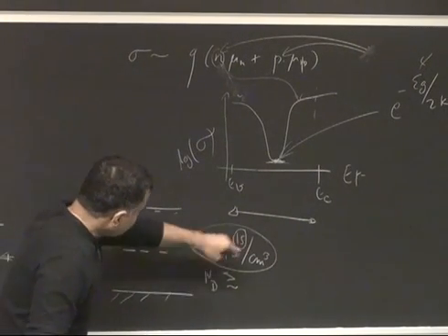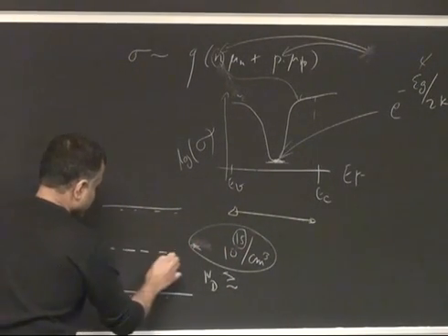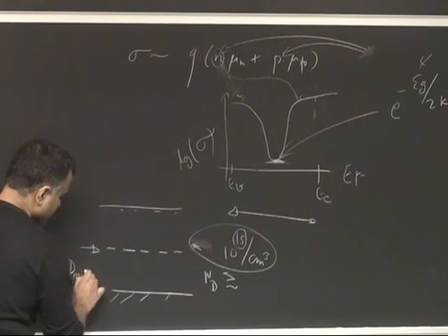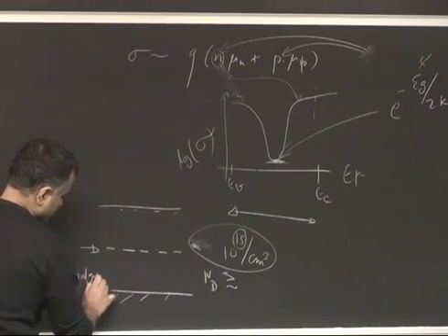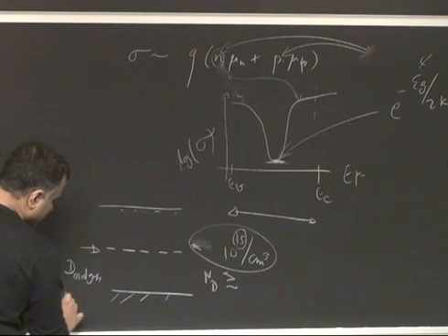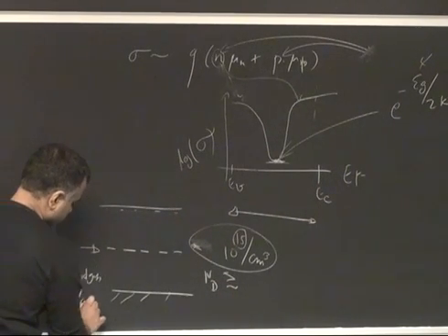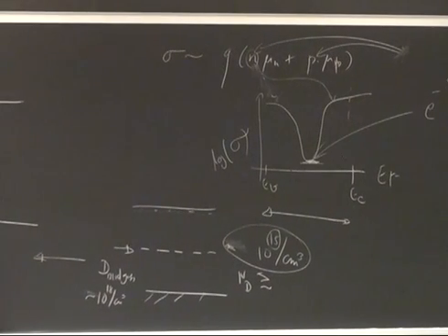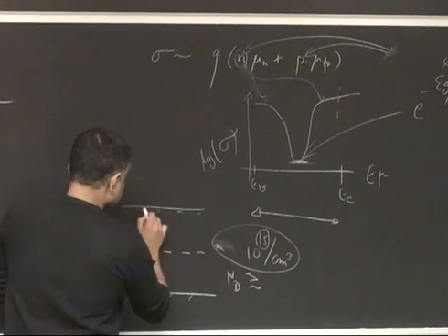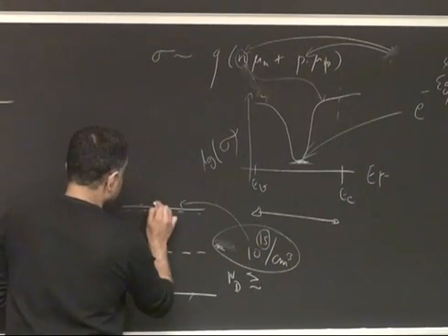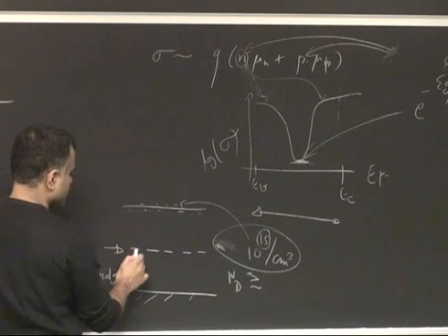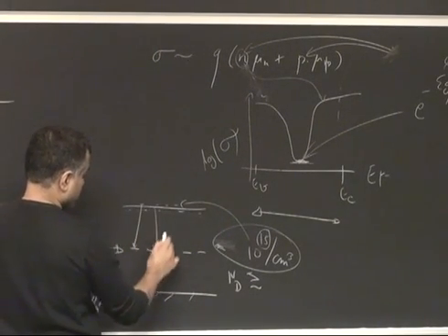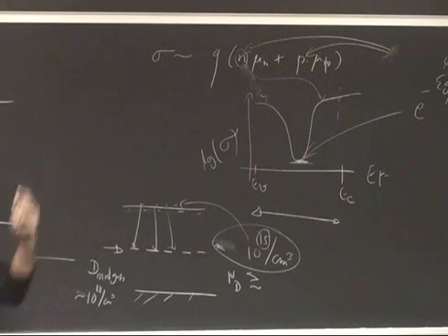So if you have such dopants and you put in a deep level, say mid-gap states of density, let's say, 10^18 per cm^3, then because of these unintentional dopants, you will have 10^15 per cm^3 electrons here. But the job of these defects in the middle of the gap is they're going to basically suck these carriers away completely, just remove them from the band.